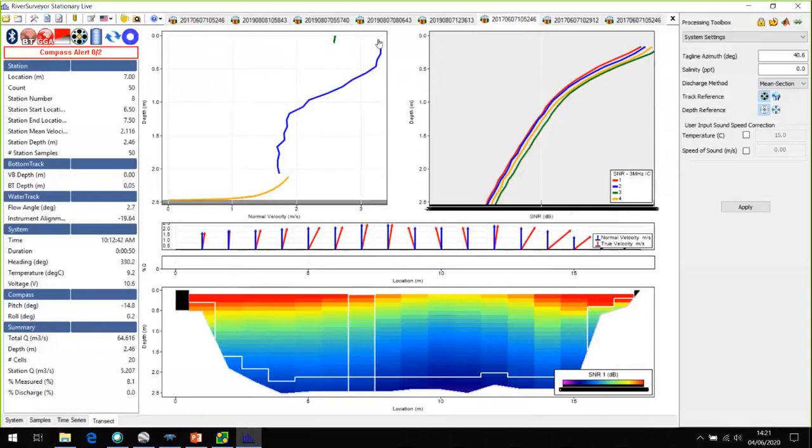I will. So before I start, everyone, I know this site has high velocities all the way down because we have lots of current meter gaugings that were done very well to show that both slightly less than this stage and higher, there's higher flows than this is reporting. And down here somewhere at 0.6 depth, there's higher velocities than this data is all showing. This velocity does not look right for a high flow gauging at this site. So could you switch the velocity in the bottom plot, Rob?